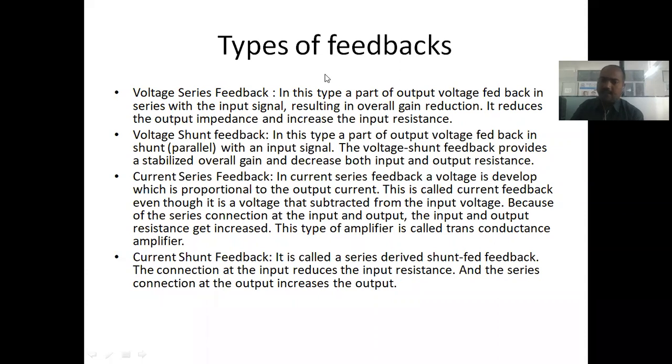No. Right. See, why does it not happen? I already told you about the maximum power transfer theorem: when the source impedance equals the load impedance. Now see, the source impedance of the particular amplifier is 1K, right? For the speaker, it is 10K. That is different, right? 1K, 10K, that is different. So there should not be maximum power transfer.